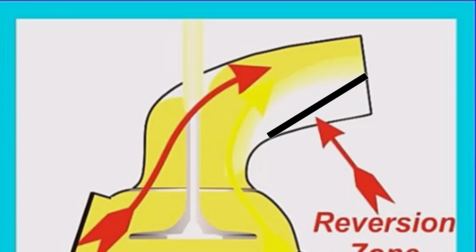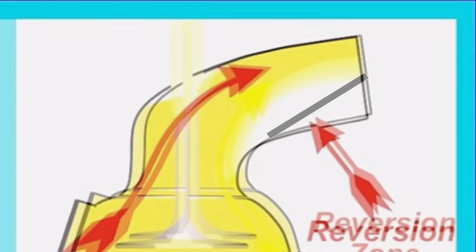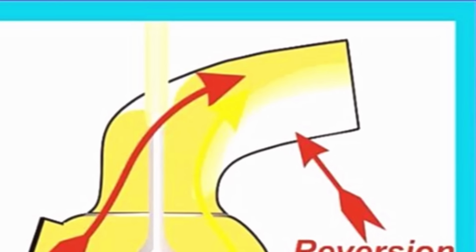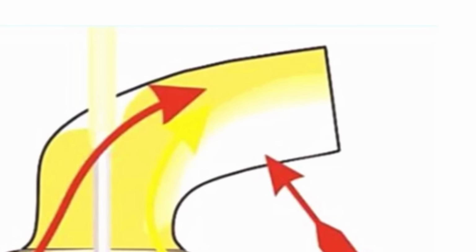Putting a plate actually in the port like this is extremely difficult. It would have been better to weld the port up and make one that was the right shape to start with. So instead of putting the plate in the port, let's put it in the header itself. This is the kind of form we are targeting.